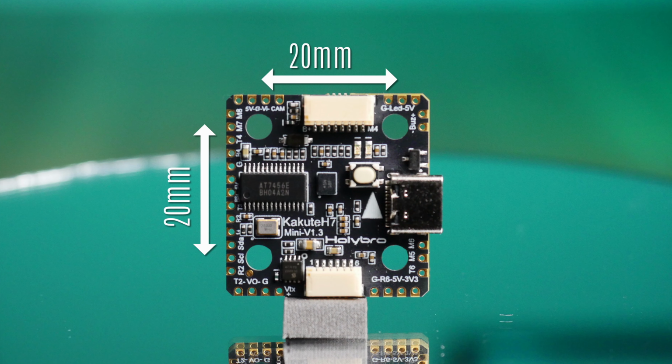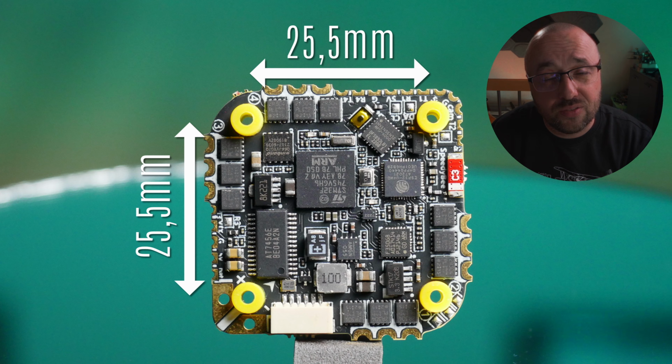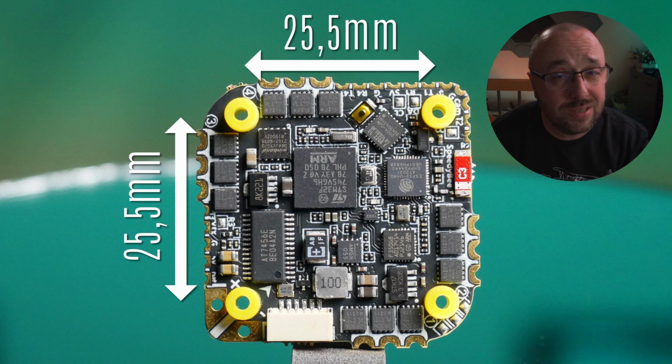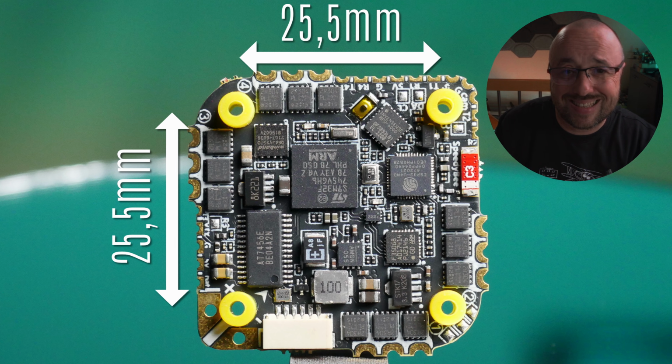The mini flight controllers have 20 by 20 millimeter hole spacing, while the 25 by 25 millimeters, usually rotated 45 degrees, are usually reserved for the all-in-one for the twig-style drones. Yes, of course, there are drone frames that can fit both 30 by 30 and 20 by 20, but usually when you have a frame designed for the 25 by 25 rotated 45 degrees, this is the only flight controller you will fit. Not always, but usually, so pay attention.